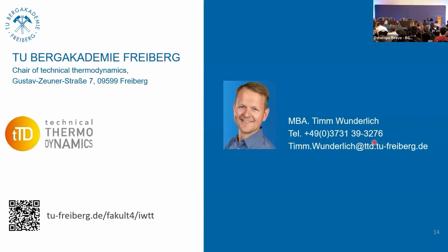The mine water power plant at the Reichezeche was operating for several years. They are now more or less closed because the treatment gallery Rotschönberger Stollen is under construction, so we can't get monitoring data for the last couple of years. But the power plant was built, it was run, and we monitored it. And yeah, COPs of 4 to 5 in the wintertime and 10 in the summertime.